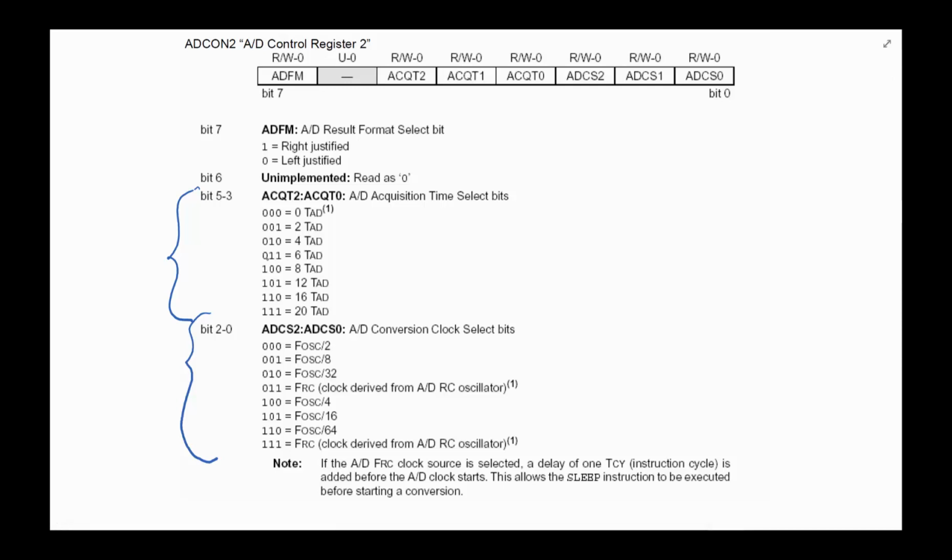And I think the biggest way I can explain this is the slower you run it, the more accurate you're going to get the answer, because you're going to let things settle in. And for our cases here, unless you have a good reason to do it, we're going to keep everything as fast as we possibly can, unless we figure out, hey, this is not working fast enough or accurate enough for us, and we want more accuracy.